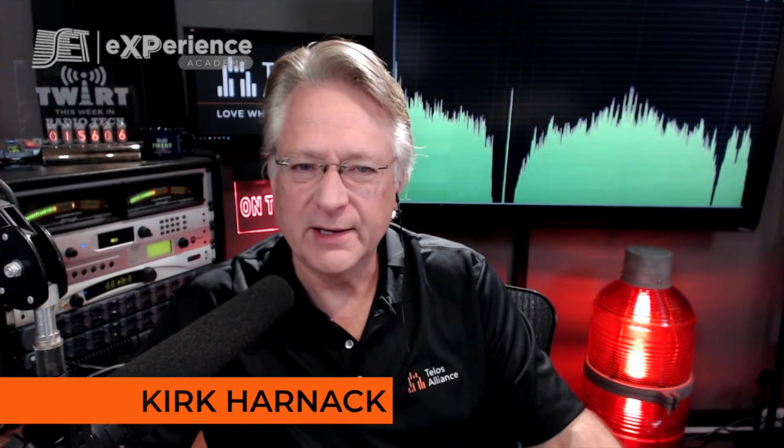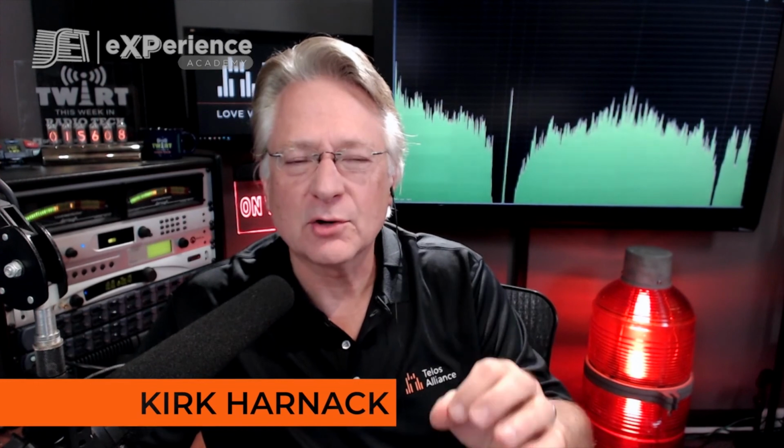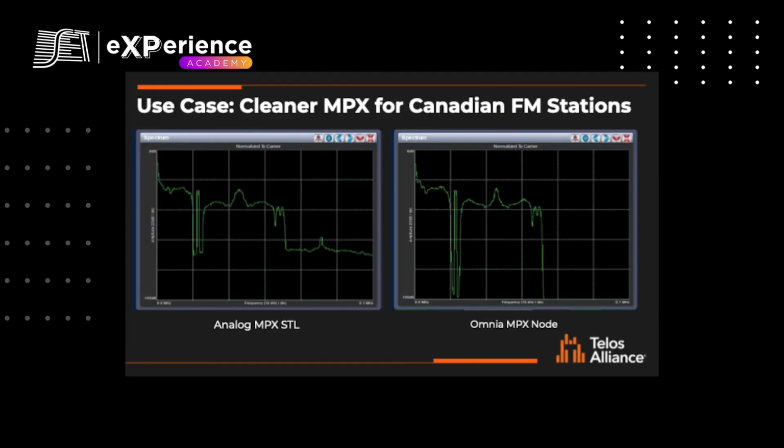Earlier, I said that Micro-MPX was a cleaner way to send audio, multiplex audio, than a traditional analog STL. And here's proof. These are 2 different spectrographs from a radio station in Canada. The left-hand one is over their traditional analog MPX STL. Now, they do have good signal on their STL, but the technology of analog wideband RF transmission only allows for a certain signal-to-noise ratio. In this case, the noise, as you can see, is about 65 or 70 dB down.